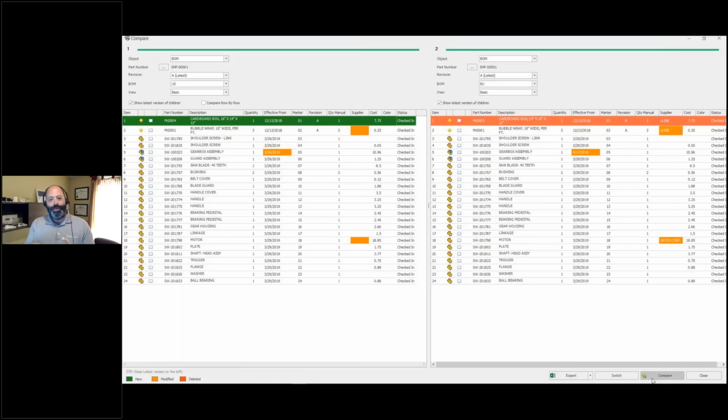And the same equipment, when they're shipping to client Y, is using a different type of roller bearing from a different supplier. So this customer has the same equipment, but whether they're shipping to client A or client B, it has different variants of the same bill of material, because one of them is asking for SKF bearings and the other one is asking for another brand of bearing, right? So this is a great way to manage some of those variants using SOLIDWORKS Manage.